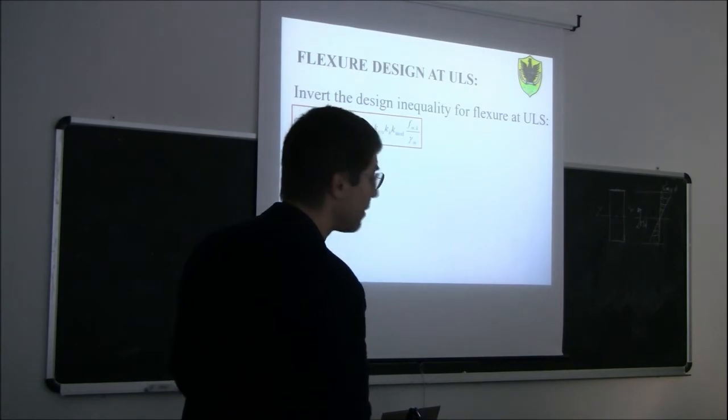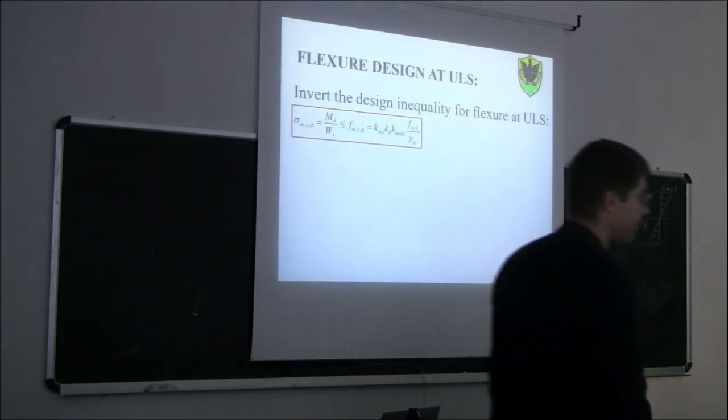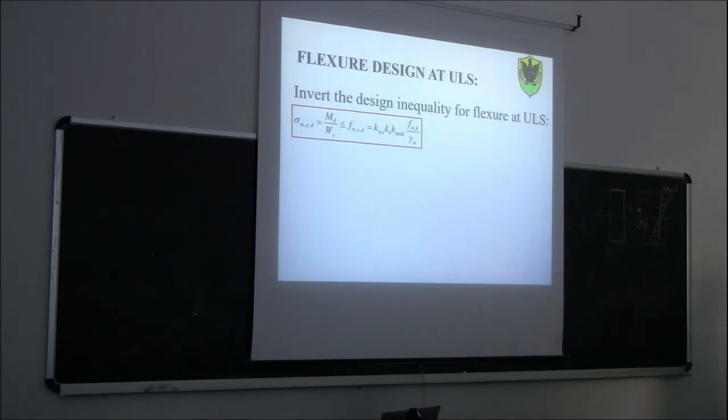Okay, now if you look at this design inequality, what are the unknowns in this design inequality? M_d. Do we know M_d when we arrive at the stage of the design? Yes, we just calculated it before, because M_d depends only on the external load. The only little problem is that in the external load there is also the self weight, which depends on the cross section, which we don't know yet. But M_d we know. W_y, section modulus. Do we know the section modulus of the cross section? No.